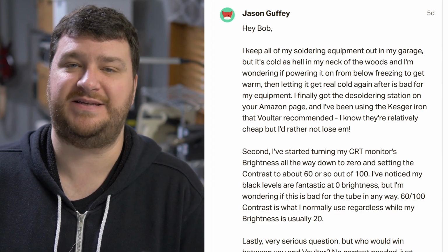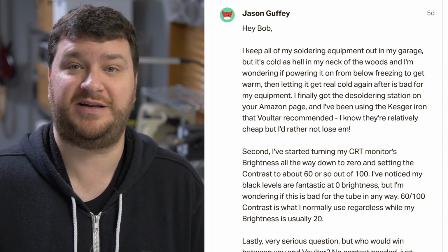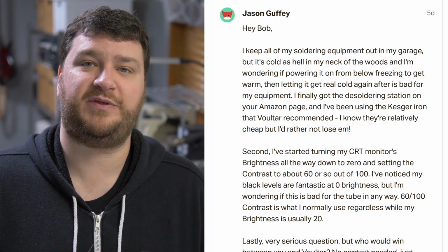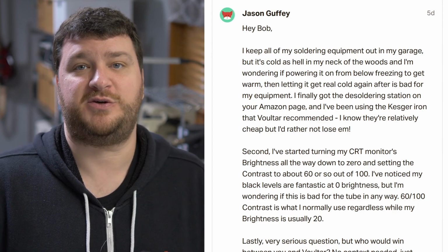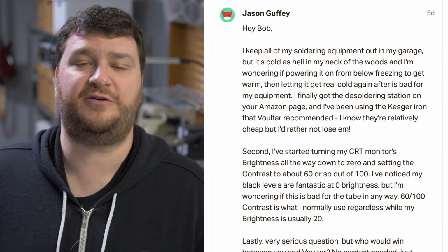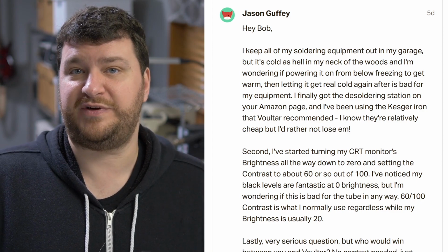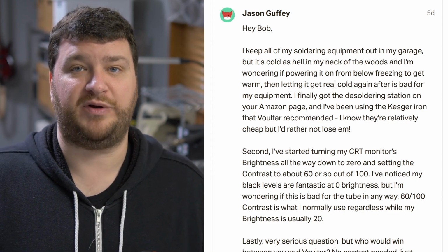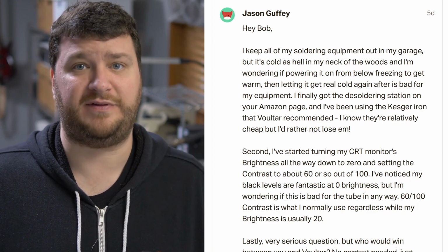But how bad is it actually? In a perfect world, you would keep every single piece of electronic equipment in a humidity and temperature controlled sealed room, but that's not realistic at all. It's just something where you would want to decide investment versus effort. So if you found yourself a D24 calibrated BVM or like the FW900 monitors and you wanted to make sure that lasted forever, yeah, if you're going to leave it out in below freezing temperature, make sure that it's not below the temperature rated in the service manual, and then bring it inside and let it get to room temperature, which might take a day before turning it on. Definitely, I would do that.